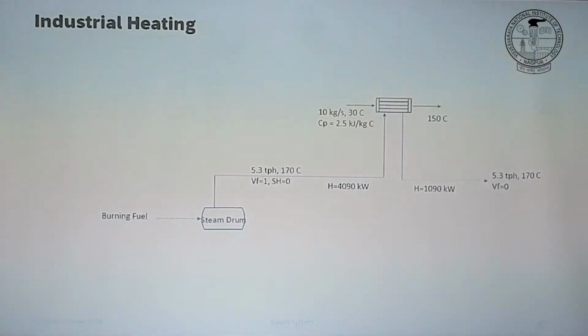Where will this steam be generated? Already by burning fuel. So we use the same numbers we used so far. Let's assume that we are burning natural gas, 47 megajoule per kg lower heating value, which already gives you the amount of natural gas we need.